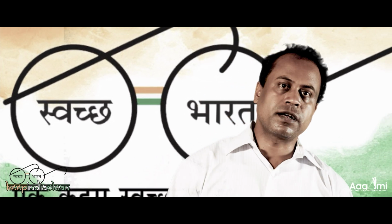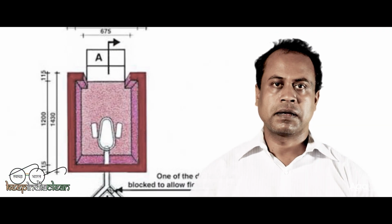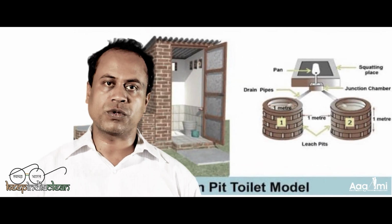We often commit little mistakes in constructing toilets which make them dysfunctional, like improper placement of the pan siphon, distance between two pits, visible honeycomb over the ground which causes spread of smell, and drainage of rainwater into the pit.